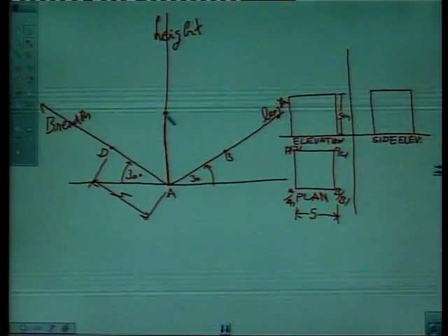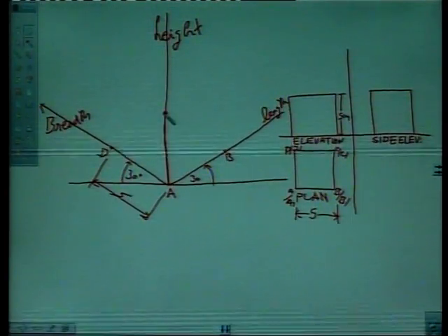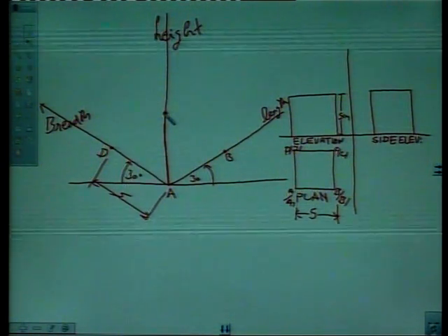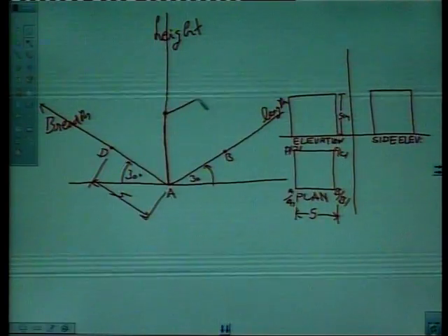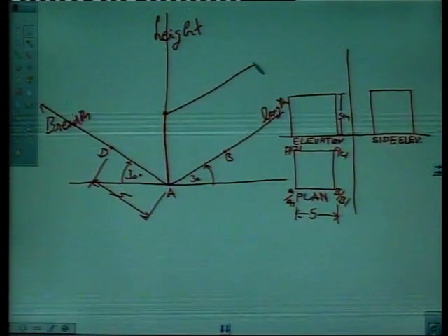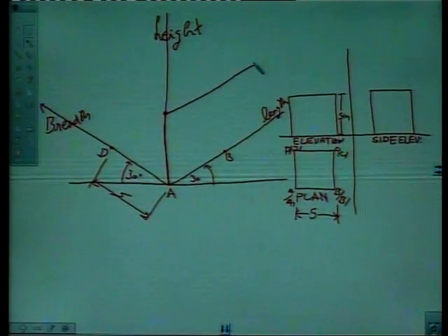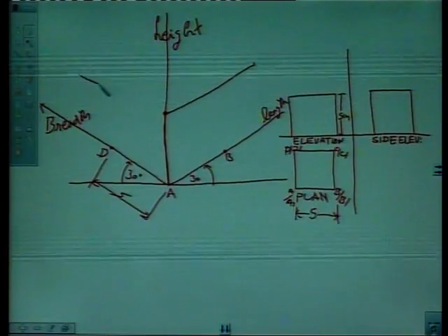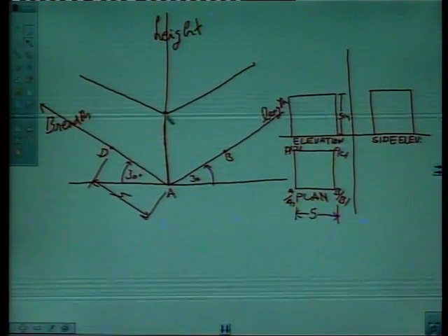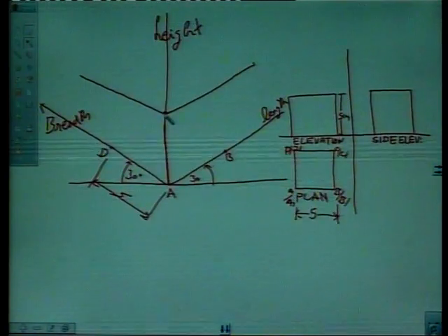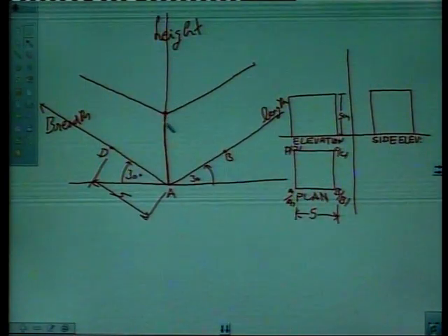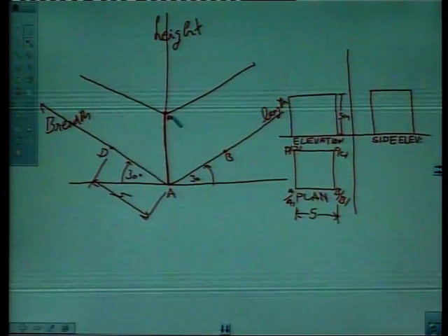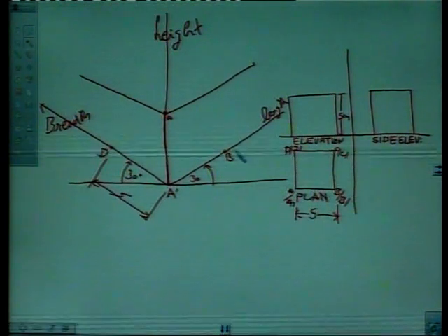Now how to complete the drawing? Okay, draw a line parallel to line AB from this point, like this. This AB and this line are parallel. Similarly, draw a line like this, which is again parallel to the AD line, right? So this height basically gives point A, and say the lower point is A dash, so we'll write A dash, B dash and D dash.